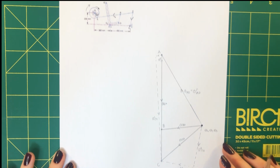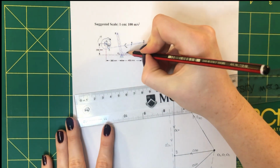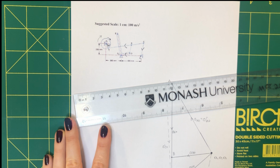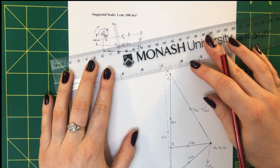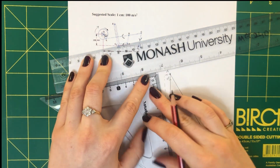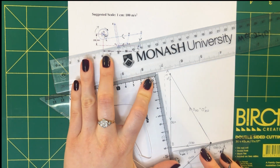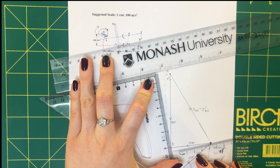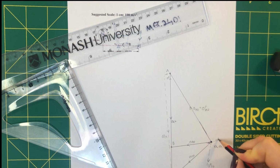So first of all, I'm going to draw in D relative to the fixed point. So D relative to O means my radial acceleration points towards point O. Put the ruler along the link, set square along the ruler, first one, second one, and this value is very small. So I'm going to give it an arrow and then radial DO.